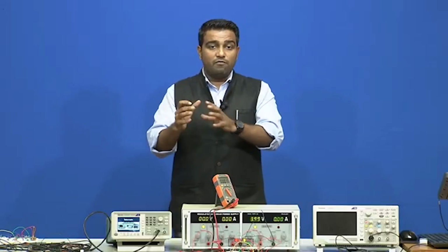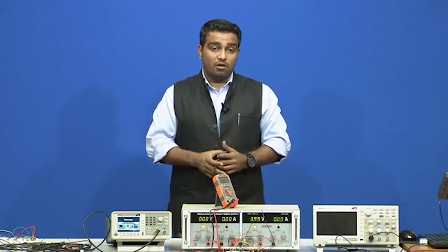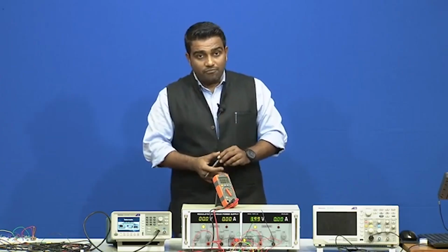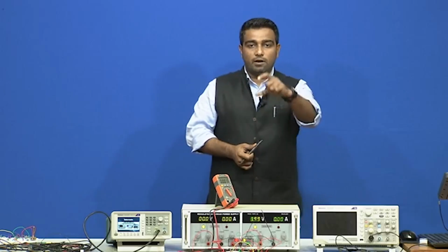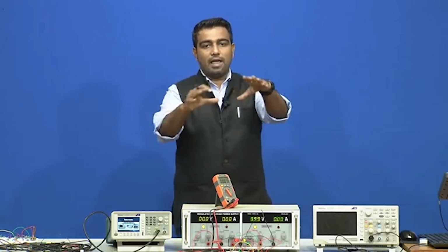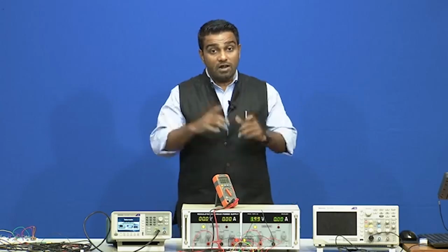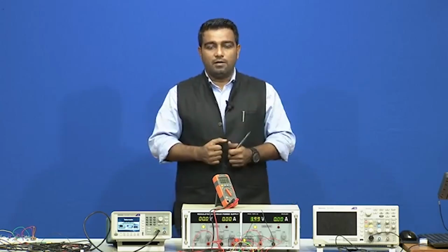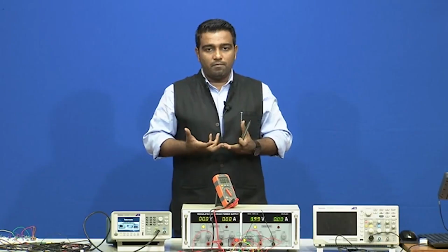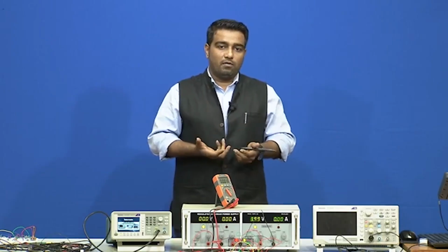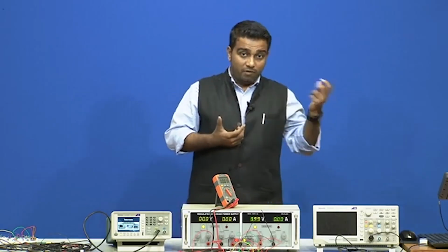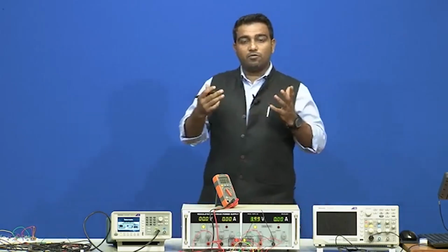Now, we can understand that if I want to remove the loading effect from the output of the sensor or the output of the potential divider when I interface the electronic module, I can use the non inverting amplifier. But what if I use a buffer between an inverting amplifier and a potential divider? Will the buffer solve the problem? Buffer is what? Voltage follower, right. We have seen the voltage follower circuit in previous modules.